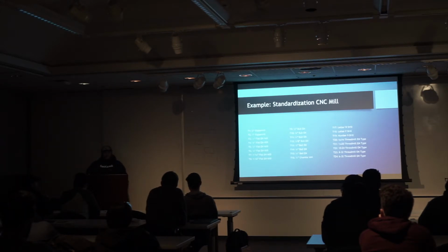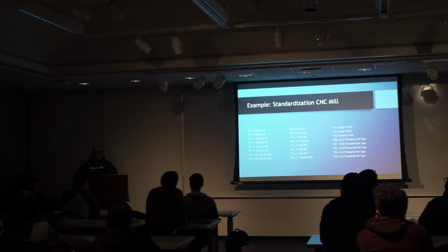So yeah, you notice that our maximum tools was 30, but I've only standardized 24 of these tools. So the other 6 tools would be for building any special geometry that our standardization doesn't cover, right? You guys are never going to be able to standardize to a point in which you can get every single part out of the standard tool list of 30 tools without severely limiting what you can actually do.